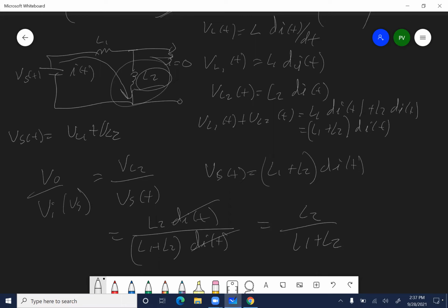And you can also expand this to current divider if you want. We don't have to go into a lot of detail. We probably will never use voltage and current divider, but I don't know if you were ever taught that in 111 or 112. You can use voltage divider rule with capacitors and inductors, in farads or in henries, and get those ratios set up. You don't actually have to convert those to impedances and do the calculations this way. You can directly do it in DC and keep everything as a farad or as a henry. And it works perfectly fine.